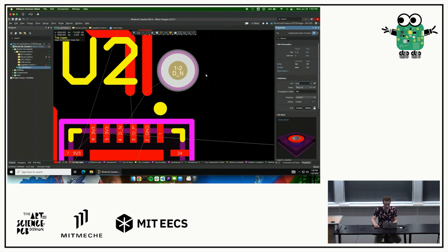And then if we notice now, there's a little air wire going between the via and the trace itself, and so we can use that to route through the via, go to the bottom side, and then come up over on the other side. If that makes sense. Yeah?